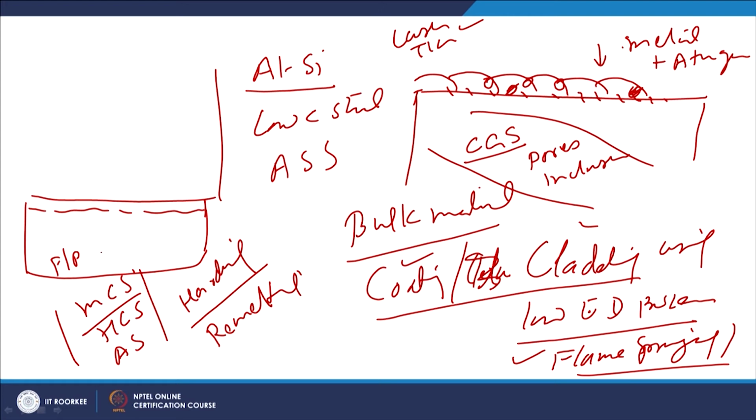So, if these are the main phases, when we apply the approach of remelting using laser or TIG or electron beam to this kind of steels, then remelting followed by rapid cooling will cause the transformation of ferrite and pearlite first into austenite after the solidification, and then due to the rapid cooling it will cause the martensitic transformation.